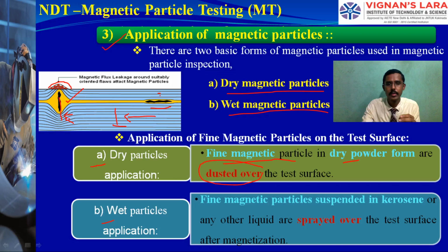If you put powder, it sticks wherever it lands. But when it is in liquid form, it floats over the entire surface, so an equal thickness is spread. Whether it is 10 drops or 25 drops, it will be equally distributed over the surface. If it is equal, the thickness of the sprayed layer will also be equal, so indications of color, darkness or anything else will be equally visible.